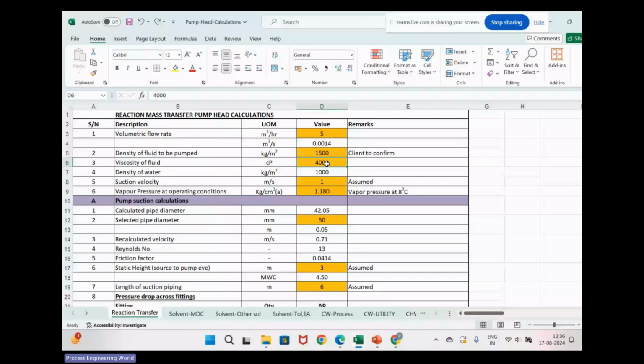Do you know a viscometer? R&D scientists have an equipment called a viscometer. They have spindles of different sizes. They take a sample of the reaction mass, fill it in the viscometer, and run it at certain RPM, pressures and temperatures. At different temperatures, they note down the viscosity at different RPM.